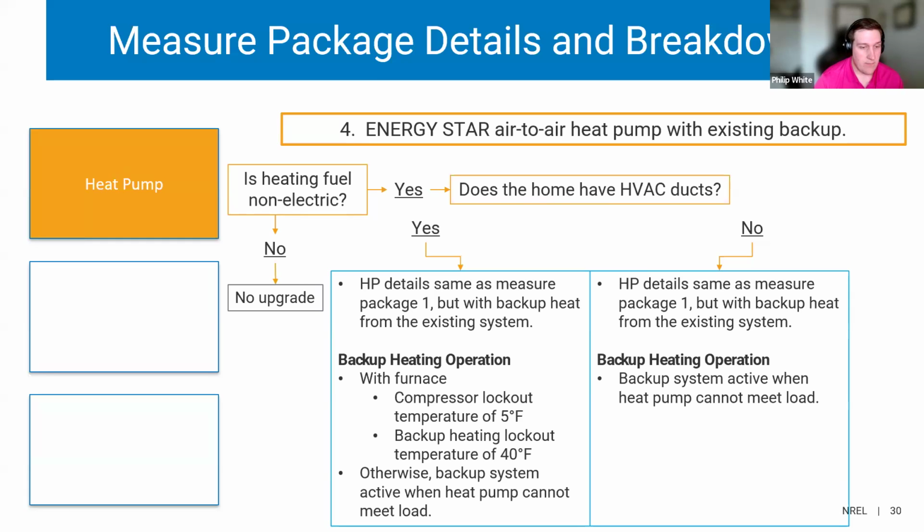And the people with expertise helped us land on this 5-degree Fahrenheit compressor lockout and the 40-degree Fahrenheit backup heating lockout.